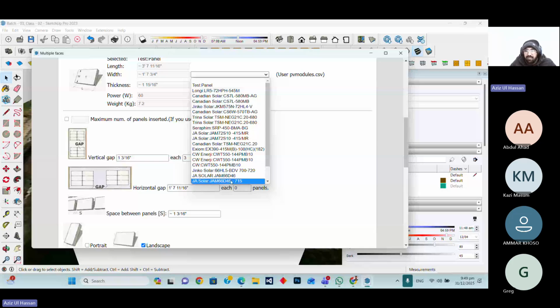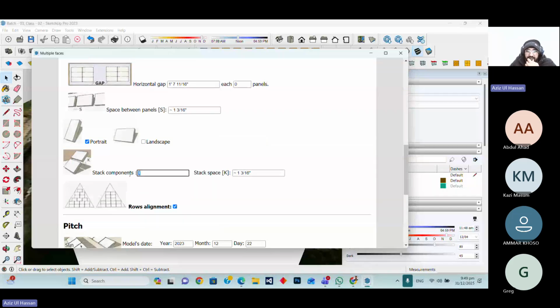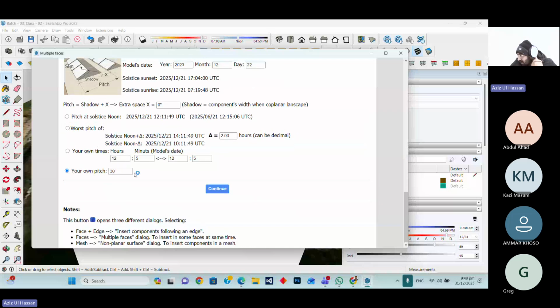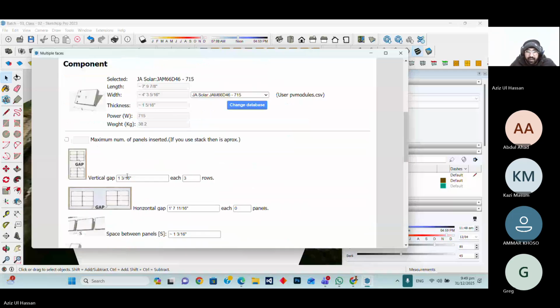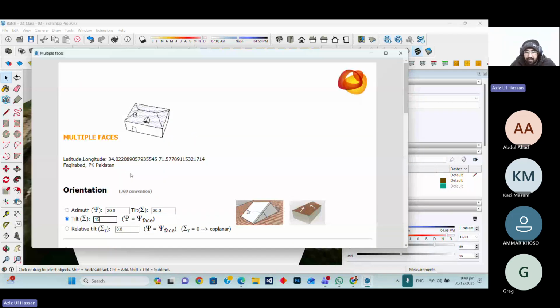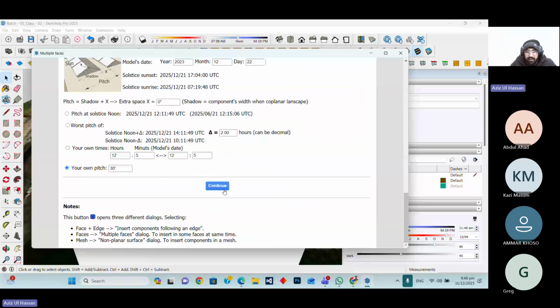So we have just made the two portrait PV module structures there, and then we will make the pitch options. Here I just give them a pitch of 10 meter. So 10 meter is 30 feet as per the 15-degree tilt angle. So I have just clicked on that, and we made that option.